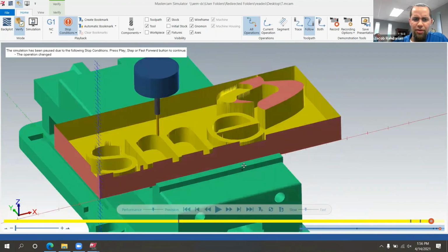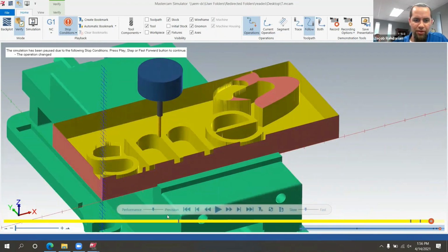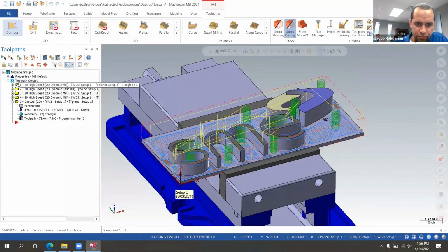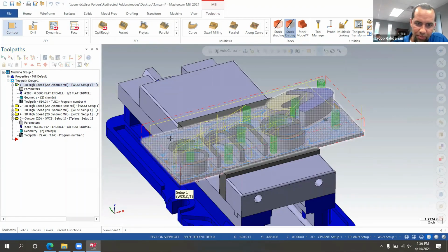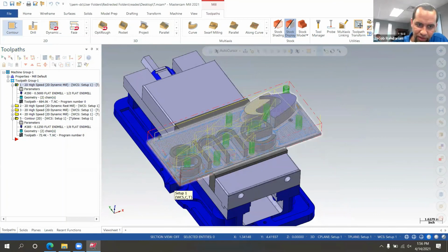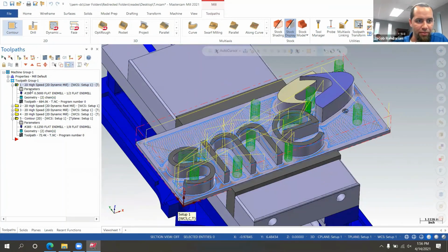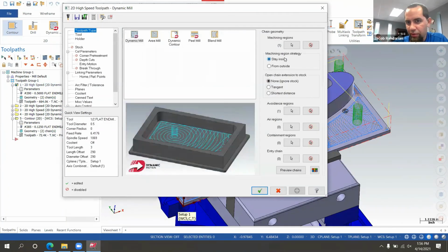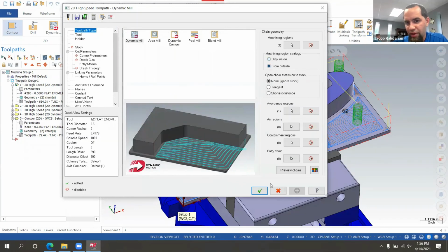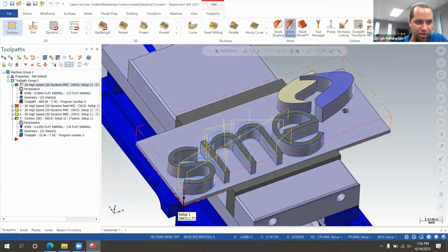All right, so we goofed something up by leaving the skin all the way around there. Let's take a look at that real quick. So that's going to be this op. You can see that this tool path is not extended beyond the periphery of this part. We definitely want to see why that is. Well, here it is. It's because I've stayed inside instead of going outside on my strategy. Really, that's going to dirty everything up. So let's regenerate real quick.